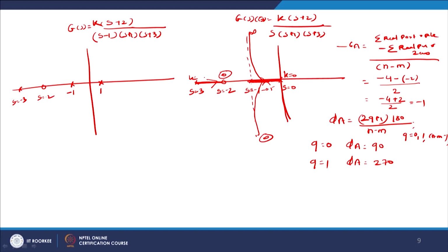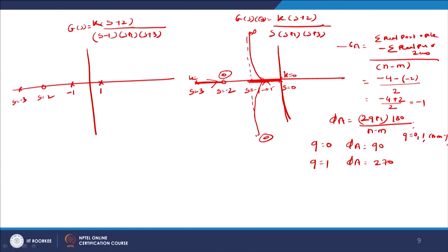Sometimes it happens that students are working on a project, and in simulations they are getting results. But when they implement the same thing in real time, they say the results are not coming, because in simulation we can get results, but in hardware, in real time, results are not obtained. So if you use the classical approach, this can be a possibility. Here also we find that in this particular example, for k varying from 0 to infinity, your system is stable. But if you take this example in real-time applications, this is not possible; the system is unstable.